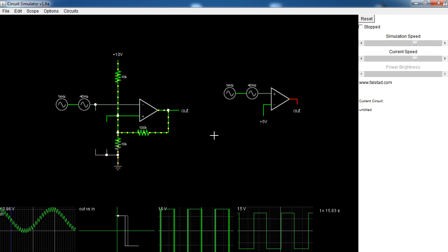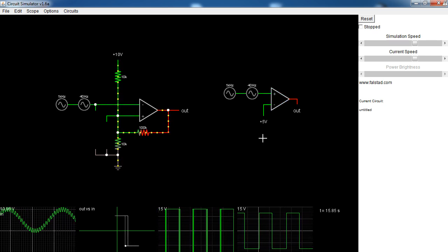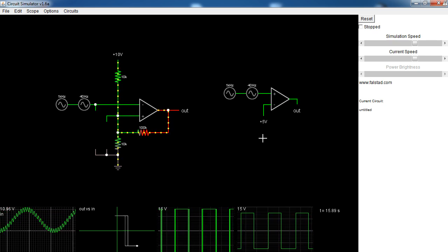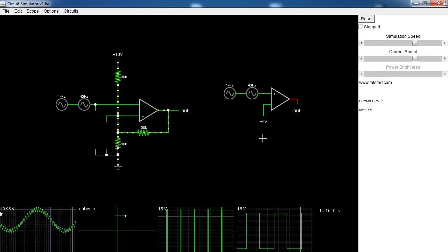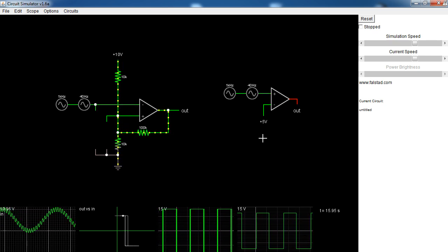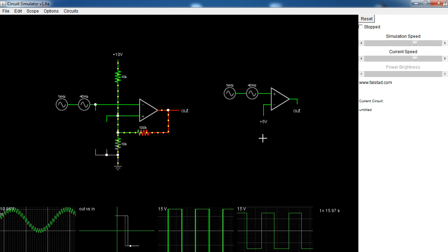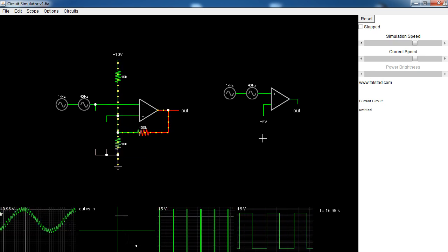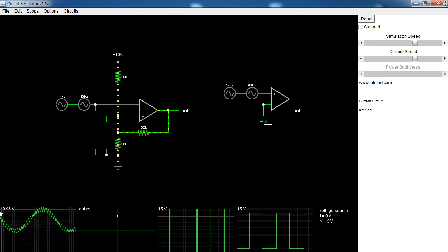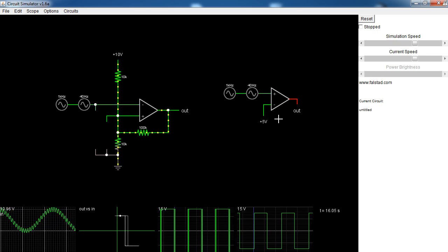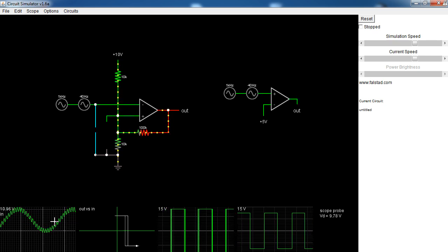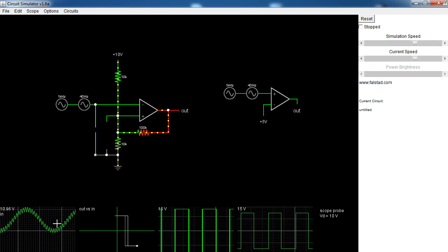Now, what is a Schmitt trigger useful for? You can get Schmitt trigger inverters. An inverter, if you know your digital logic, gives a low signal out if you put in a high signal, and a high signal out if you put in a low signal. What a Schmitt trigger inverter will do is remove some of the noise from that normal inverter. It'll get rid of the jitter so that you have a little bit of window. Again, Schmitt trigger is very good at removing this sort of indecisiveness. It will get rid of some bouncing in a digital signal.